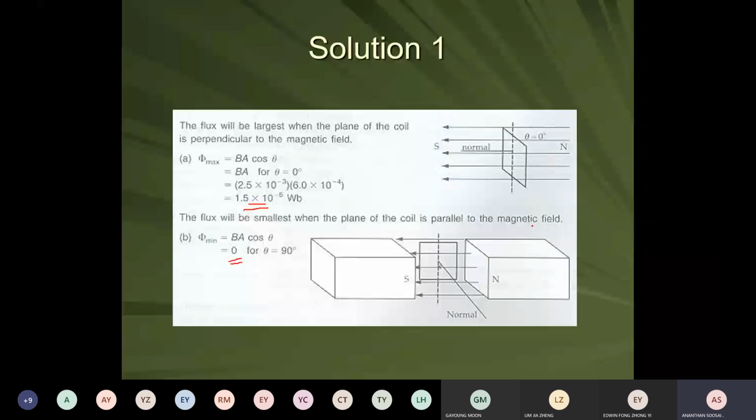So when the coil makes one round, how many times is the flux going to be zero? Let's say at the beginning it was vertically positioned, north. The flux is zero at 90 degrees of turning, and after that at 270 degrees. So you get another time the flux becomes zero.